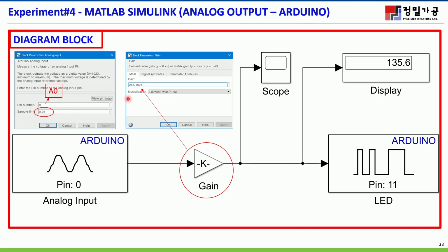That's correct. And again, you have to convert, because this pulse width modulation input is 0 to 255, right? This represents the duty cycle. 0 is 0%, and 255 is, I'm sorry, 100%.